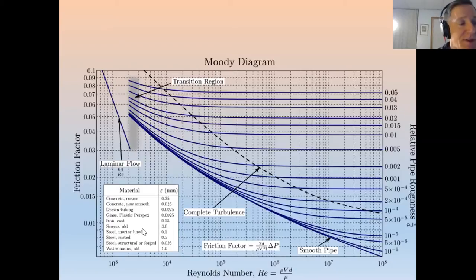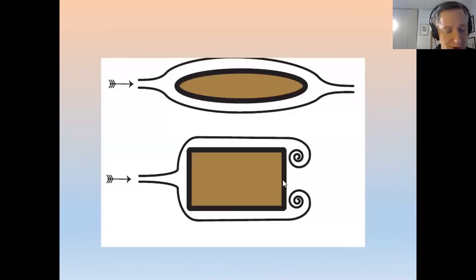What this is saying is that things that have higher friction, going up on the scale, have more drag. Rougher things have more drag than smoother things. So here, this has to be for piping: smooth pipe down here, rougher pipe up here. Roughness normally gives you more friction drag. You'll notice some other terms here connected with turbulence and laminar flow, which we'll look at later too. It has to do with the boundary layer, which is an important issue. That's kind of straightforward in terms of friction drag, because you're used to that in your everyday life. Like sandpaper has more friction than leather.